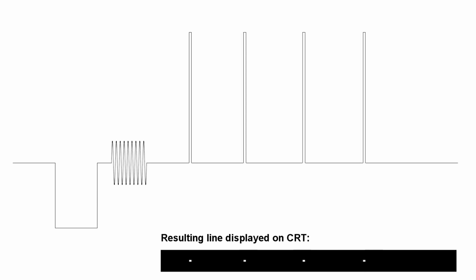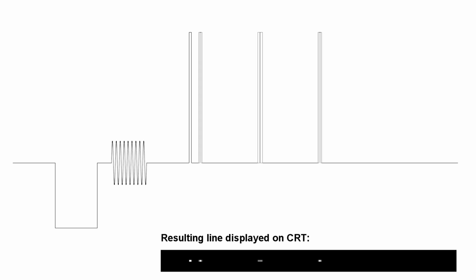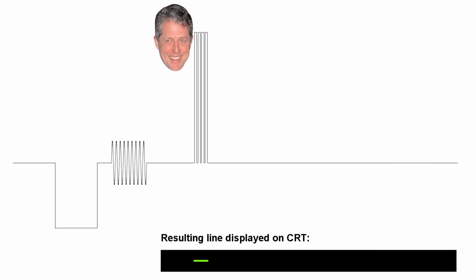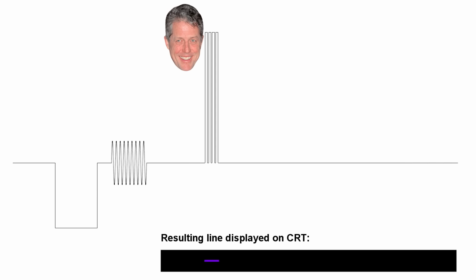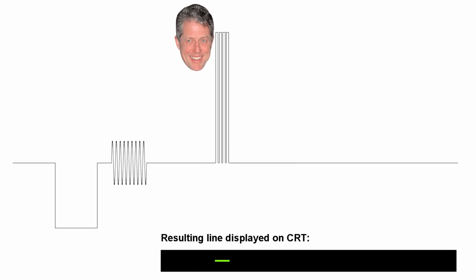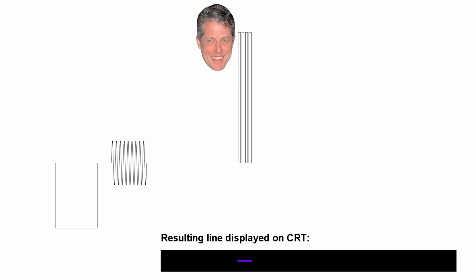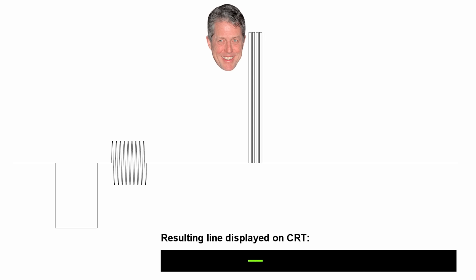Ensure your pixels are small enough such that the luma generated by patterns of dark and light pixels appears in a frequency close to 3.579545 MHz. And ensure your pixel locations on the screen will cause the luma signal to phase shift from that color burst signal you sent to predictable degrees that result in the color you want. Easy peasy, lemon squeezy, and we're all done.